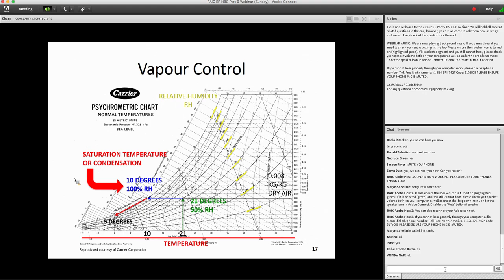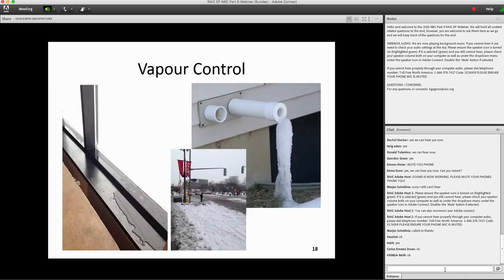So where do we see this? This is where we see what I just explained to you very quickly. On the left side, there's a window. This is a coffee shop in Ottawa that I took the picture from. A lot of paper cups, a lot of coffees coming up. So that's not a leak on the window. That's condensation throughout the day. The air that is inside is at 100% relative humidity, so the frame is cold and you get condensation there.